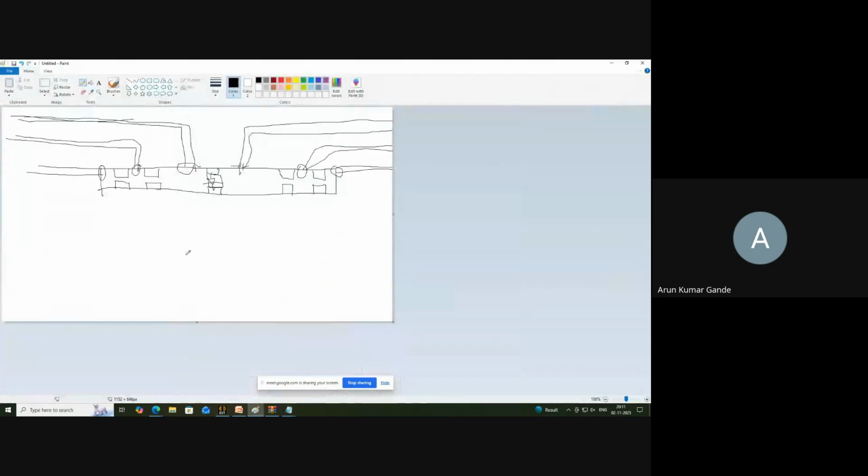So what we can have here is an inductor, then here you have your capacitor, then an inductor followed by a resistor or a capacitor, and that is connected to your L here, right? We can simplify this by combining these two into a single inductance, and then the LR or LC circuit, whatever you have, this series LC can be easily converted to a parallel LC. We have fixed formulas for converting series into parallel.